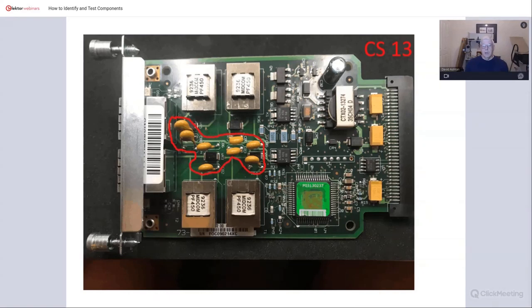They will hold a current of 170 milliamps, and they'll trip at a current of 340 milliamps, which is double that, which is a usual specification for one of these things. Again, pretty useful little devices, give you automatic protection on a circuit. You don't have to fuss around replacing blown fuses. And also, these are fairly low rated. They're 170 milliamps they'll pass. So you won't find a fuse that'll blow at anything like that.